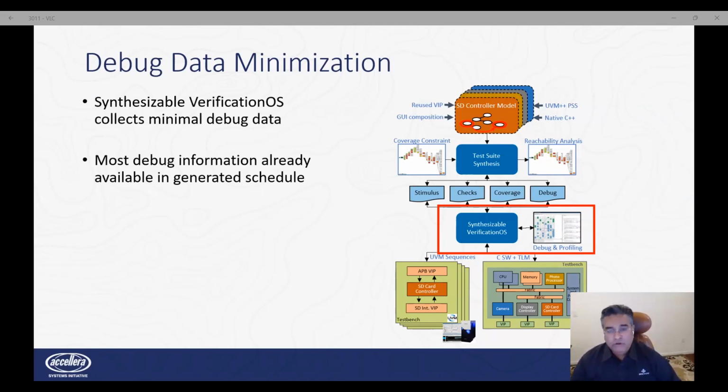Usually we can figure out what's going wrong straight from the high-level debug. If we can't, only then must we rerun the test case in emulation with FSDB enabled so we can get our low-level waveforms, or take the test case back to simulation and run it over there.